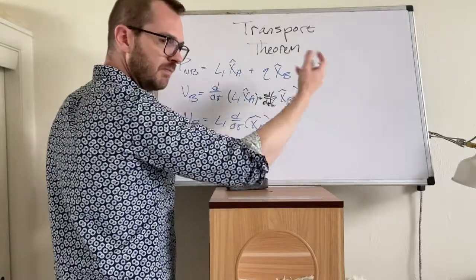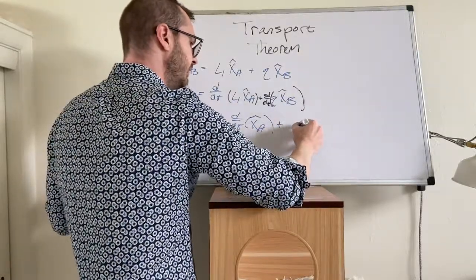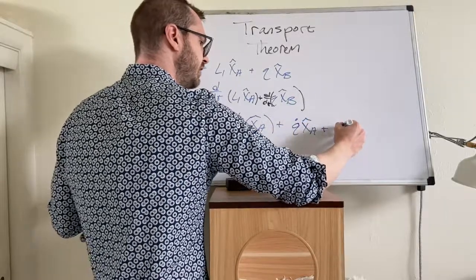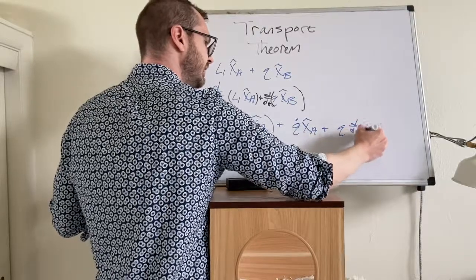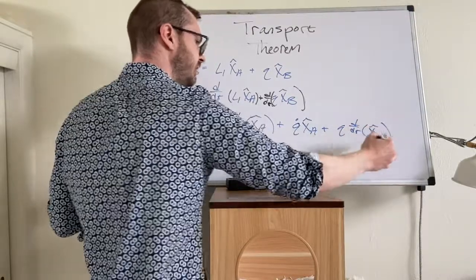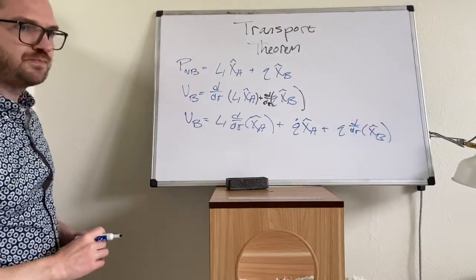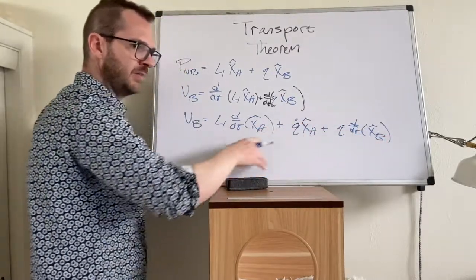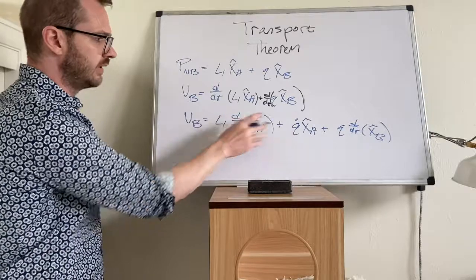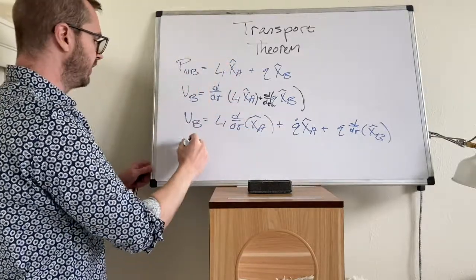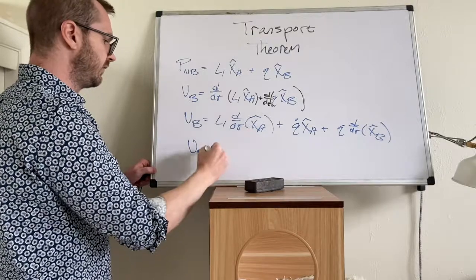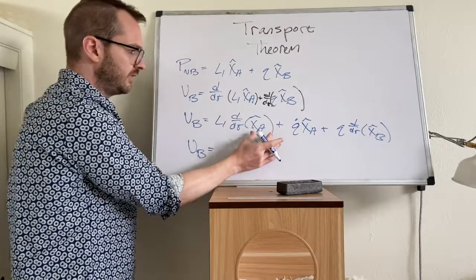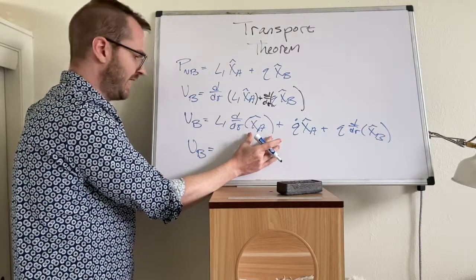That's the translating and rotating at the same time. So we'll have ddt of the scalar Q, which we can do very quickly, and then Q ddt of x hat B. Okay, we have two of them now. I have ddt of A and I have ddt of B. So twice now, two points in this problem, can we use transport theorem? So VB is going to equal this first piece. We can do transport theorem on this piece. We're taking ddt of the A frame, x hat A.